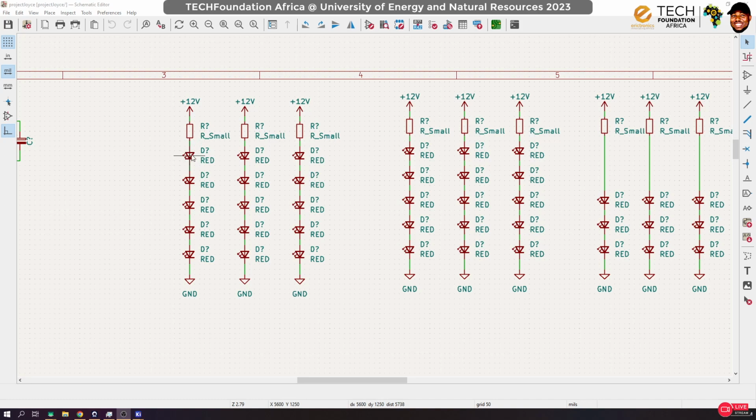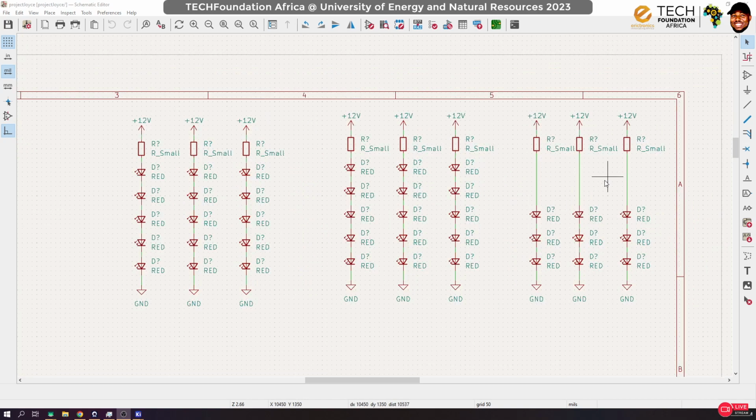Okay. So in order not to do that, we are replacing one LED with a resistor so that this resistor serves as a protective resistor. Okay, so in total, the 5 LEDs will consume 10 volts out of the 12. That means that this resistor that we put here has to handle the 2 volts excess. Okay, and so we have one serial line, another connected in parallel. We'll be arranging them together to form the red LED. And we also have something similar for amber and something similar for green.